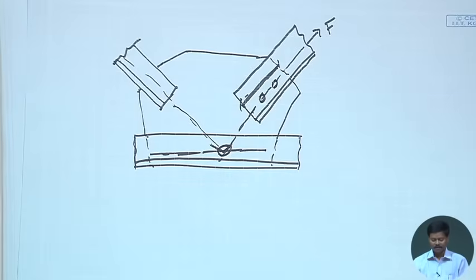And if the length of the gusset plate becomes larger, then the weight of the gusset plate will be more, and if the weight of the gusset plate becomes more, then the dead load of the structure itself will become more. That is why it will not be economic. Economic in the sense that if the gusset plate size becomes more, and we know for a particular structure the number of gusset plates is huge, so the total weight of the gusset plates will be huge.